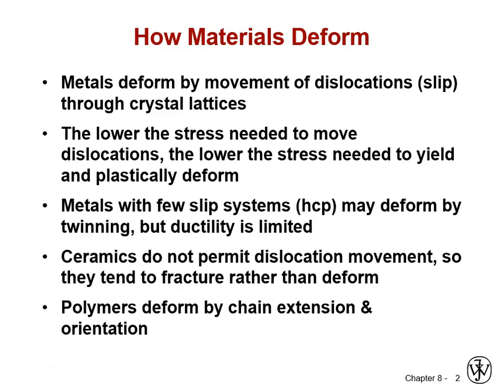And the most glaring example of that is the hexagonal close-packed system, which encompasses quite a few engineered metals, zinc mainly, and so these materials might deform easier by twinning than by dislocation movement, because although in the case of hexagonal close-packed or HCP, there is one close-packed set of planes, but only one. So those dislocations will initially move easily on that and then quickly max out the capabilities to sustain more deformation.